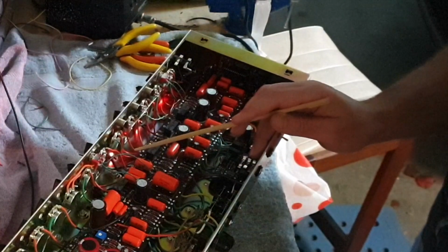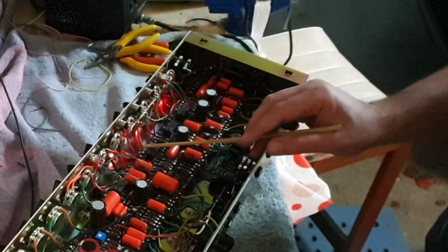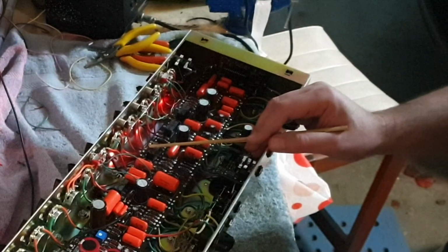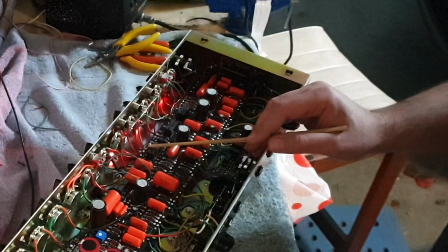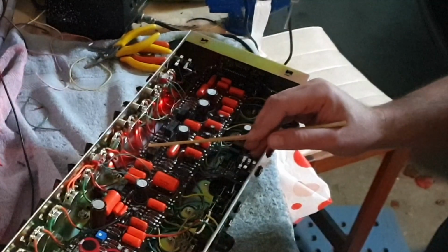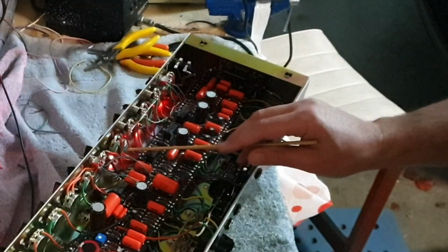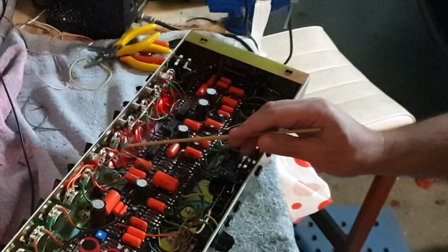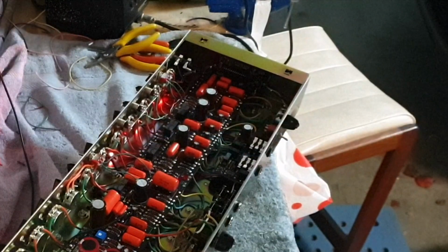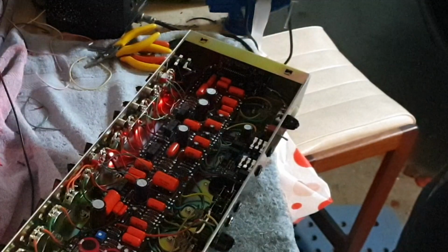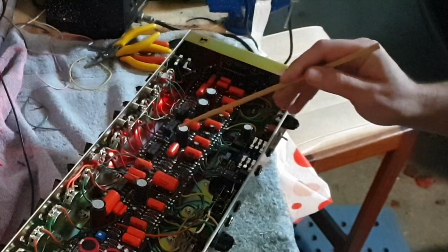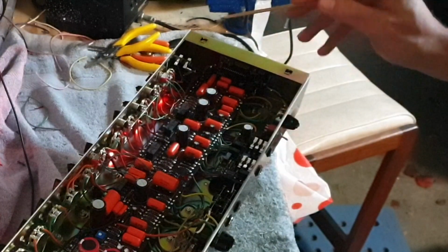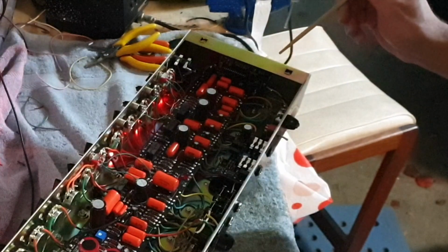Use a 1K resistor. It's shown in the MC2 layout, the most recent one. I'll show you how to wire those up. It's a 1K dropping resistor for your LEDs. If you run your LEDs with a 470 ohm, it's too bright. They're just like torch lights, way too bright. If you try to run the LED with no dropping resistor at all, you'll blow it, and it'll emit a little bit of smoke and it'll be game over. A 1K resistor is right for 12 volt on these red LEDs. Seems to be a nice balance.